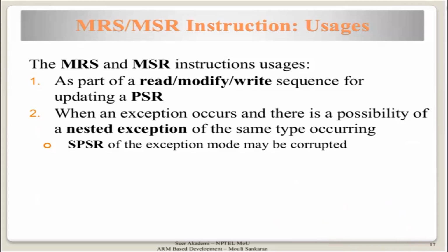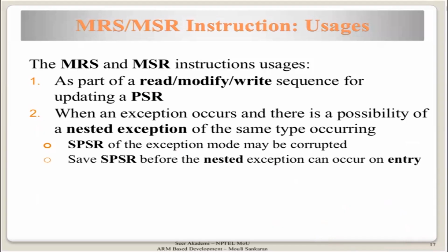I don't want to go into the detail now because it is out of context. Let us talk about that when exceptions happen. Right now, take it from me that when nested exceptions happen, you need to save the value in SPSR into the stack and then restore it back. For that also, you will be using the MRS and MSR instructions.